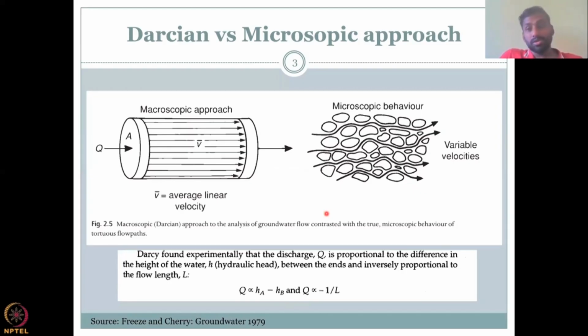Before that, just to introduce Darcy. Darcy was an engineer in France where he worked on water fountains, and he had to supply water through underground pipes to make sure that the water fountains were working properly. For that, he didn't have any equation. This was very, very old times. So what he did is he took the soil column to his lab and then derived this equation. And to date, it is one of the most accurate, very simple, but most accurate descriptions of groundwater flow in a saturated system. The assumption is also that the soil inside is fully saturated.